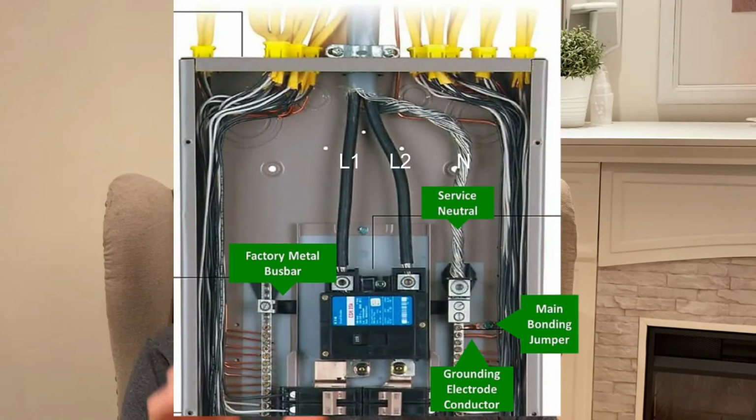And we also have to realize that there's always a connection from this neutral conductor directly to the earth, and that is for a level of safety. Again, like we just talked about, some point of our power distribution system has to be referenced to the earth so that it has a lower resistance path to discharge some of that electricity out of the system instead of passing through you. This is a basic idea of what's going on here. But you can see at the top, those are the only three conductors that we're dealing with.